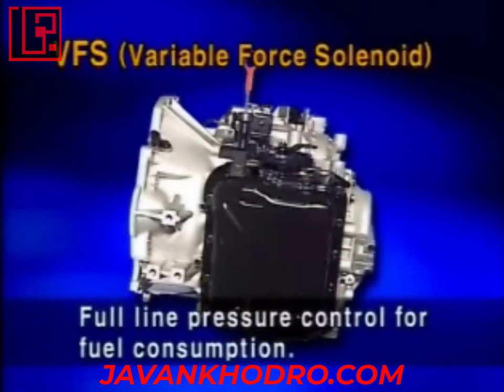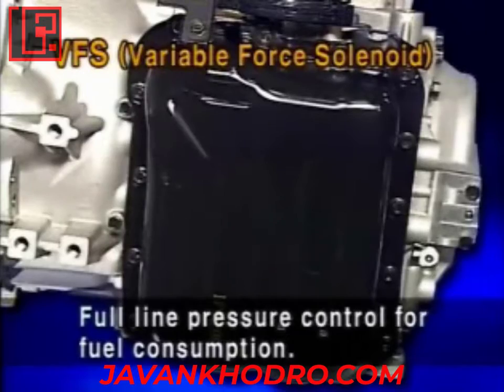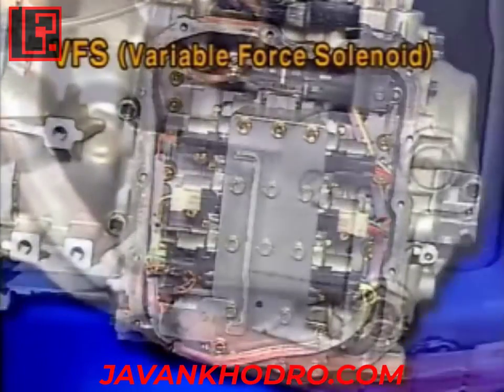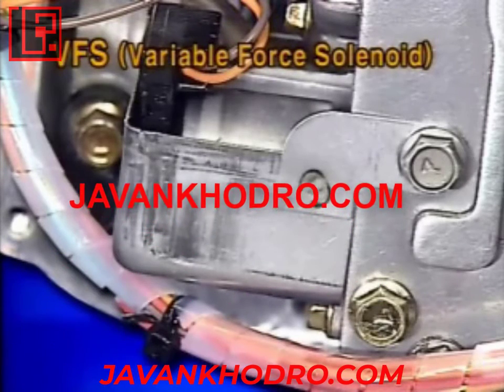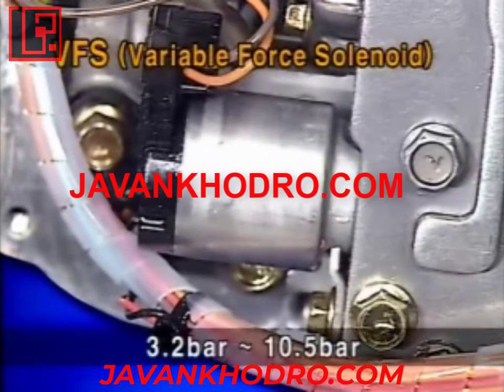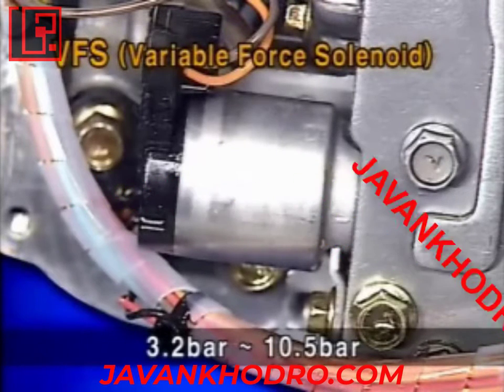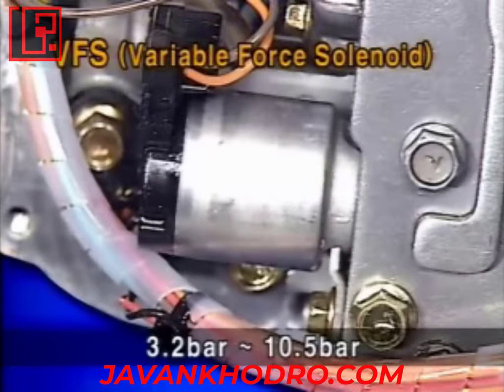The enhancing features against the conventional 5-speed automatic transaxle are, first, that the fuel consumption is enhanced by adopting variable line pressure control. As the VFS valve for the variable line pressure control is applied to the valve body, the line pressure corresponding to the engine load varies from 3.2 bar to 10.5 bar at the D range.